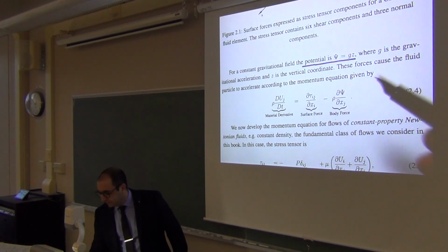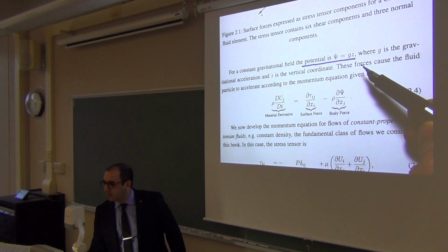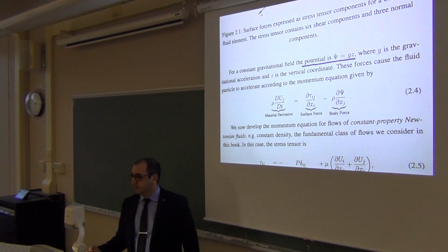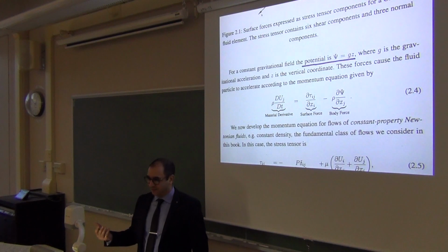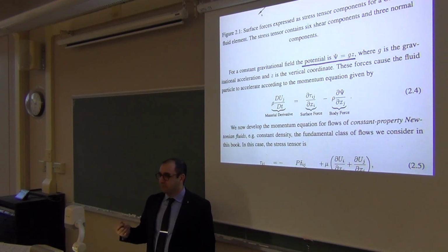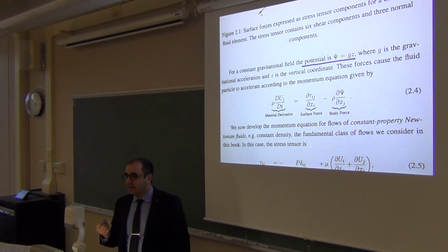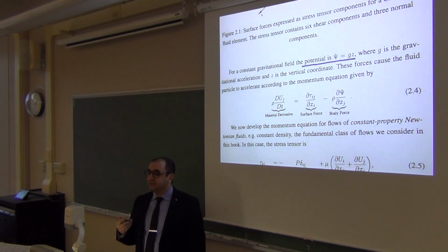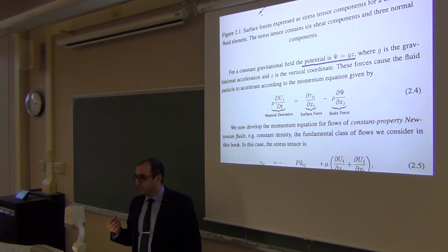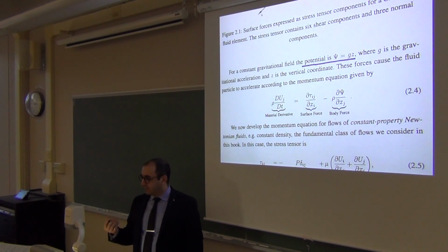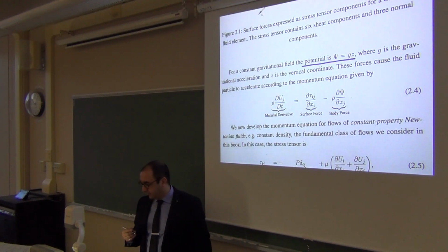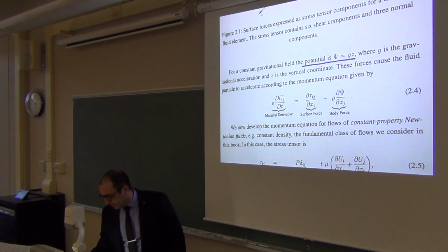This is really familiar from mechanics. If you remember, gravitational potential in mechanics is basically mgh, right? So if you drop the m, the mass term, what remains is gh, or gz here. That's a potential. And if you take the gradient of it, as we took last time, whatever is remaining is g, right? So that's how they relate. If you take the gradient of gravitational potential, you get gravitational acceleration. So that's familiar to us.